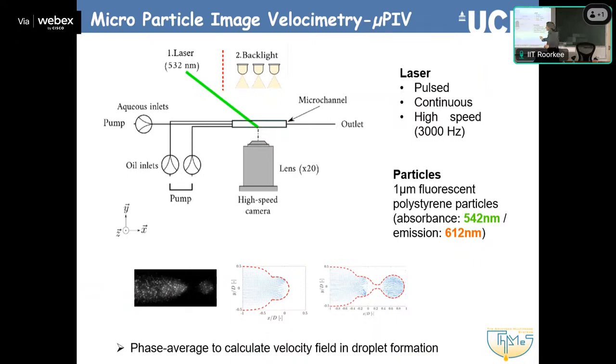So in particle image velocimetry, what we do is that we put seeding particles in one fluid, and we get images in quick succession. I'll try to do this here. So the flow moves forward. Let's take an interface, and we see the particles. It's a bit hazy, but you actually see the particles. These bright spots are particles.